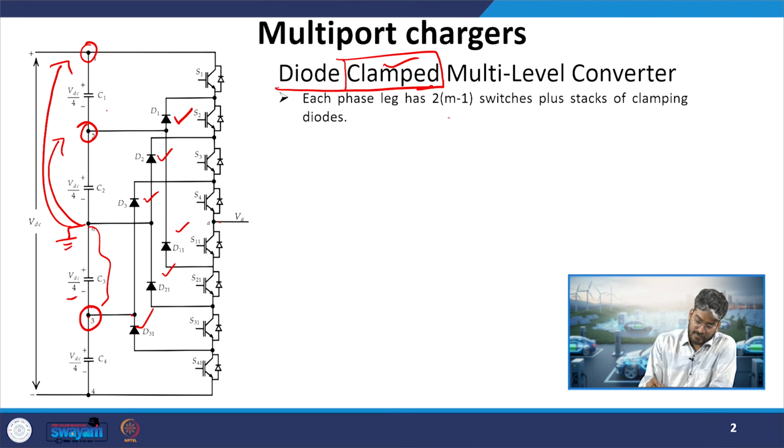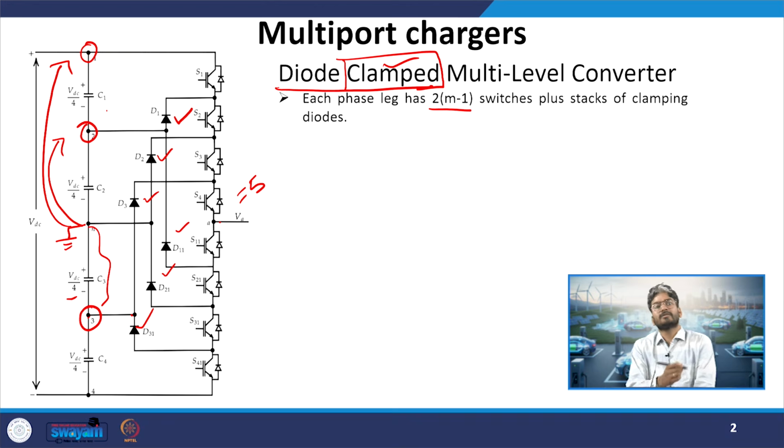So here as an example we have considered a 5-level diode clamp circuit. Similarly we can consider a higher number of levels as per the voltage requirement. The higher the voltage, the more levels, so that we will not require series connection of our devices. So what limitations do we get from the series connection of devices? The switching frequency will be very much limited when we have series connection of devices, because the dynamic characteristics or the switching characteristics will be different. So because of that we generally try to avoid series connection of devices.